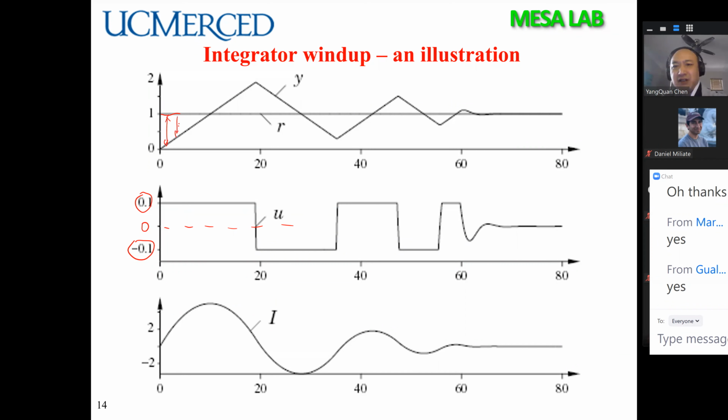You pass 0.1 immediately, so you saturate a bit, but the error is piling up, still going up, until you cross this one. Then the error is negative, the sign changes, and this goes down, but it is still in the saturation state, until you cross the 0 in here. Then you get out, and suddenly you saturate again until here. So this is my 0.